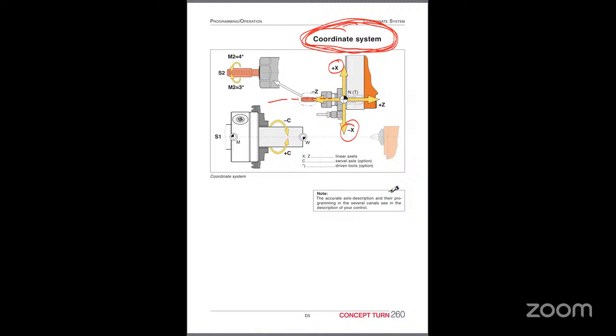This is the center of the workpiece, right? The movement from this center, outside and inside, is what is called x-axis movement. For example, this is the workpiece. If the tool is moving outside this workpiece, that is called plus x. And if the tool is reaching into the center, then that is called minus x.